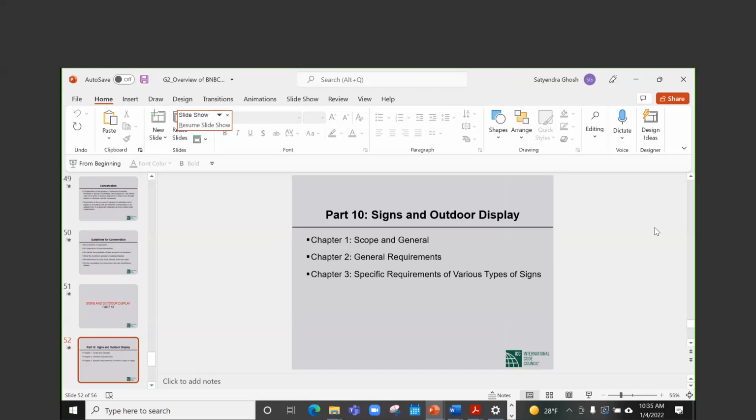So the reason for live load reduction is exactly what I said. If you have a large area, it is extremely unlikely all of the area will be experiencing the full design live load. So the reduction depends on the area on which the live load acts in one way or the other. That's what it depends on.